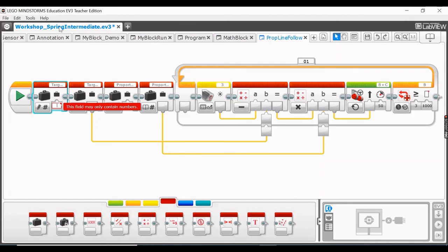If we want it to be 50, now we can edit it. Now remember what I said before, it can't be 0 or 100, because those are the extreme maximums and minimums, and you would not want to do that. I would recommend anywhere from 20 to 80, 20 being like 80% black and 20% white, and vice versa for white.